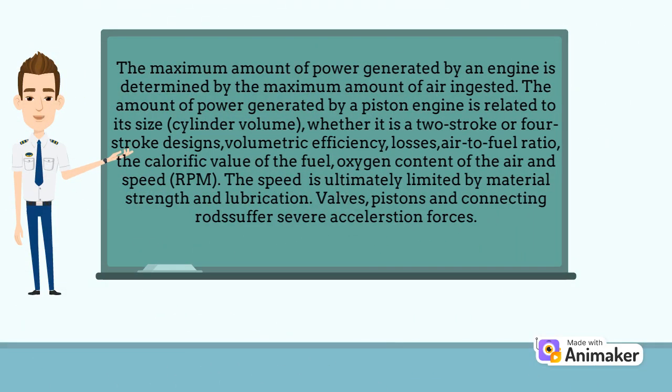Maximum amount of power generated by an engine is determined by the maximum amount of air ingested. The amount of power generated by a piston engine is related to its size, cylinder volume, whether it is a two-stroke or four-stroke design, volumetric efficiency losses, air-to-fuel ratio, the calorific value of the fuel, oxygen content of the air and speed, RPM. The speed is ultimately limited by material strength and lubrication.